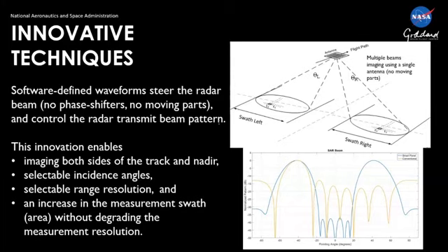Whereas this approach enables the energy to be put into two beam regions and suppress the noise elsewhere where we're not using it. We can actually push that noise outside of the areas that we're actually measuring. So it definitely improves the radar illumination.